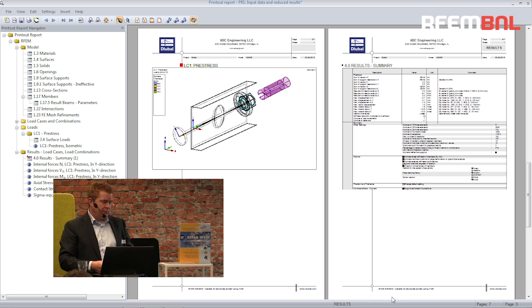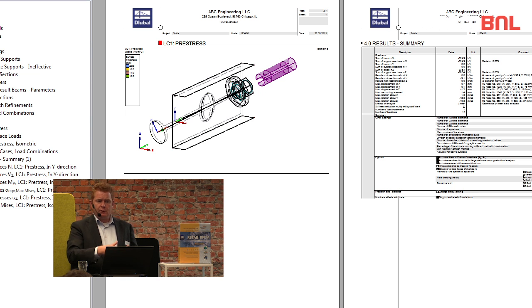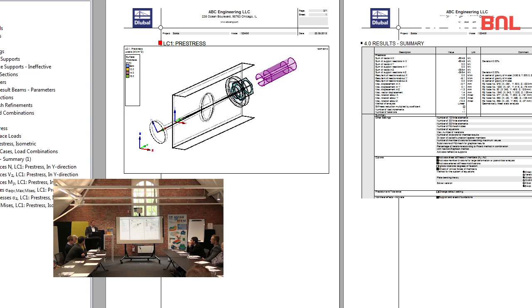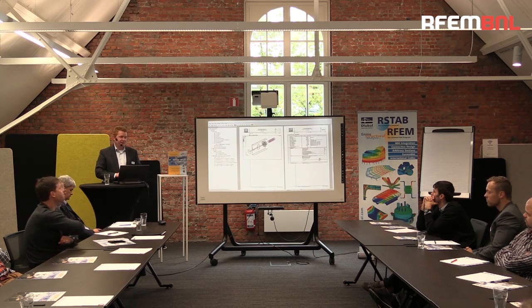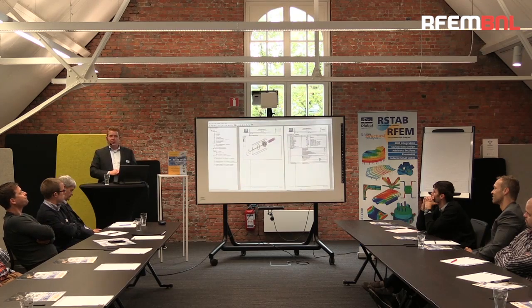So what we did: we extruded something from a solid, from a surface into a solid, or we extruded surfaces from lines. We used user-defined coordinate systems. We used copy commands. We looked a little bit at the application of loads. The meshing was there. We used tools like Result Beam, and we had 3D PDF for distribution of your model. And in the end, we had a printout report with, hopefully, the correct pictures and the data. Are there any questions?